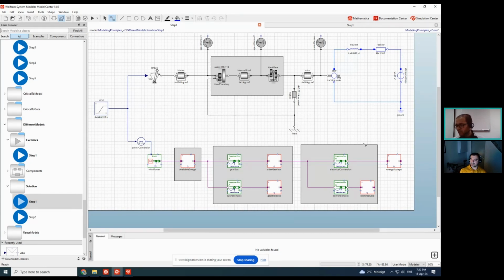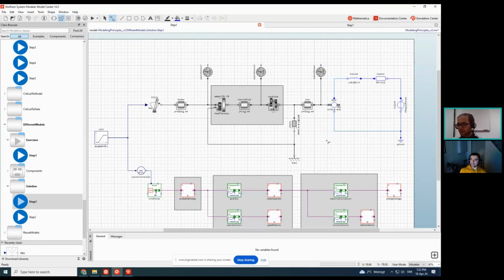It quickly gave us a picture. But if we want to go into the details of the model, like how a wind turbine actually works, we see the turbine rotate very slowly, 15-20 rpm, but by using the gearbox, the generator speed increases from 20 rpm to 1200 rpm, and it rotates so fast. And then how the conversion is constrained by the storage capacity.